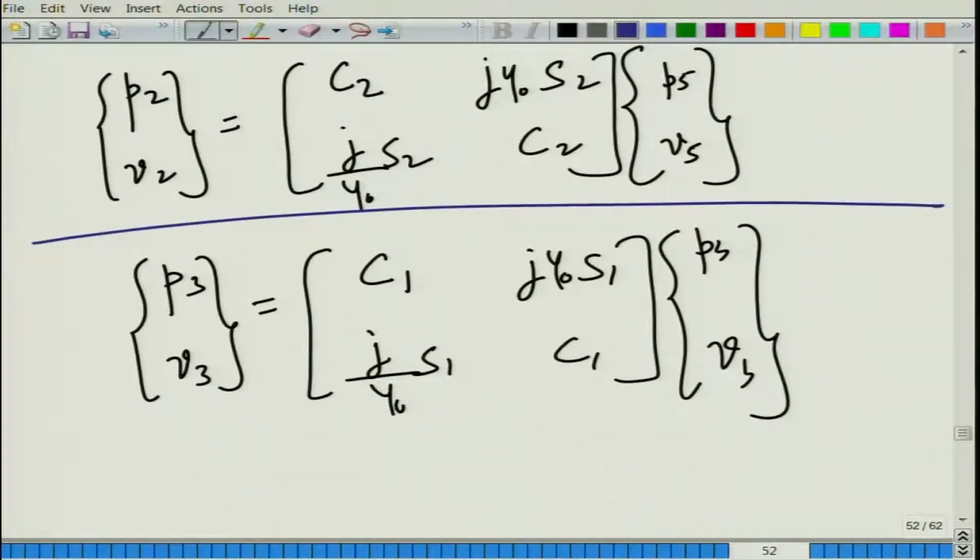Now, one needs to combine all these things to ultimately get P1 in terms of P6, V6, as we have already discussed. So, how do we go about it? Right now our focus is to quickly develop an analytical formula using some of these expressions, possibly going to Maple, and then write down a clean expression for the transfer matrix between the upstream and downstream variables. Then figure out where the resonances or the troughs would occur based on constructive or destructive interferences respectively, and validate that using a network analysis. The computational part will be done in MATLAB after we have developed the analytical formula with the aid of Maple.